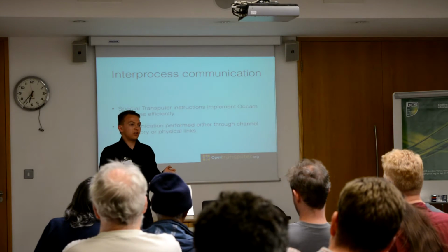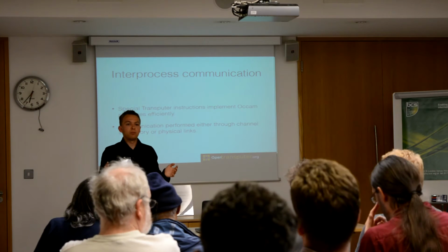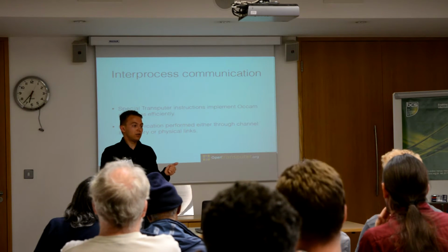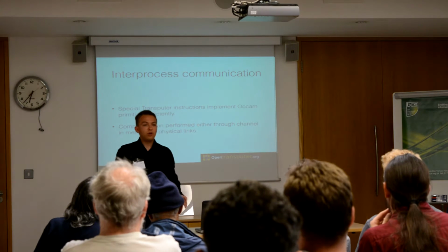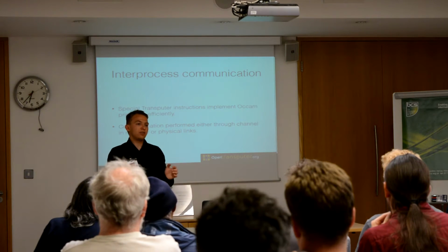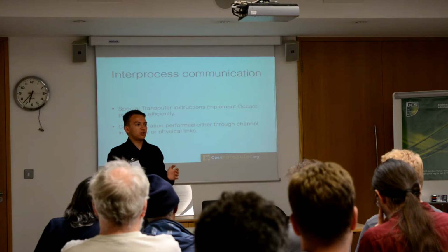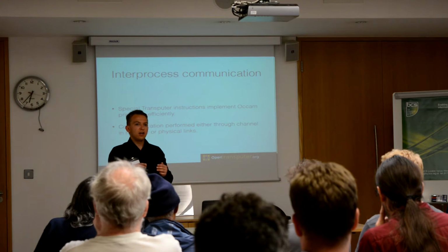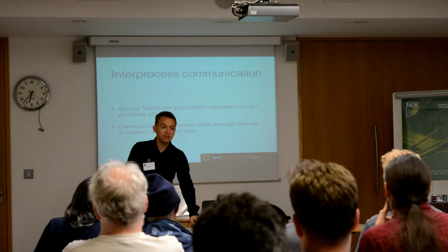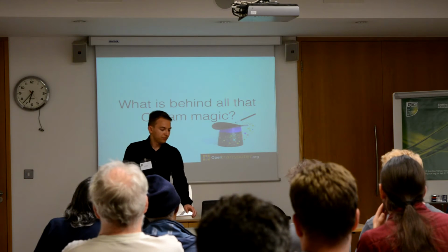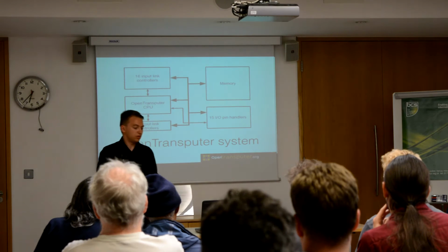So special instructions in the Transputer implement all these OCCAM primitives we have seen, including the scheduling and also the communication. With regard to communication, one has to differentiate between off-chip and on-chip communication. On-chip communication is performed by a word in memory. Off-chip communication is done via the physical links of the Transputer. And behind all that OCCAM is, of course, the OpenTransputer.